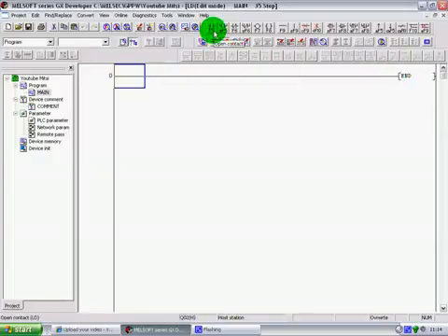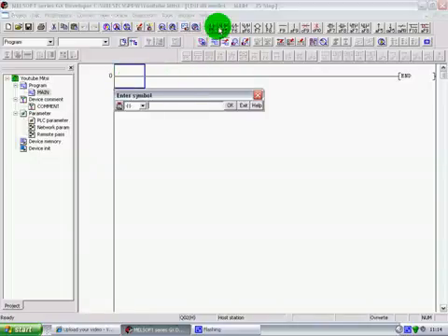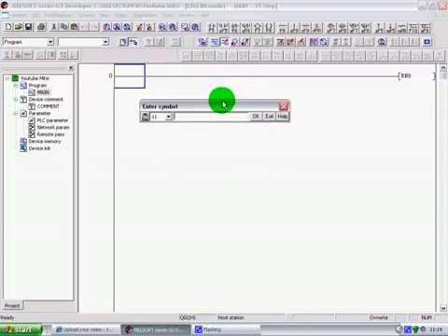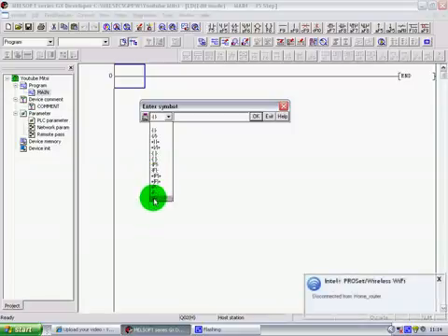What we do is select the kind of contacts that we want once we've selected part of that rung. So we'll select that point there, which is just a normally open contact, and we get a little window here. If you've chosen the wrong one, you can correct yourself by clicking this little down arrow, and you then have the choice of all the other contacts.